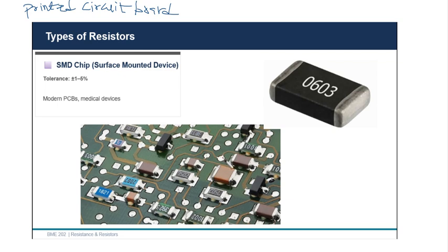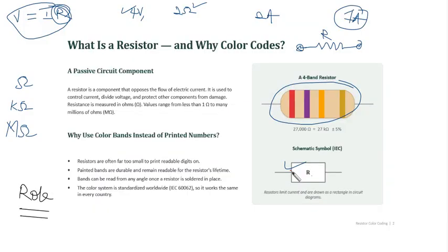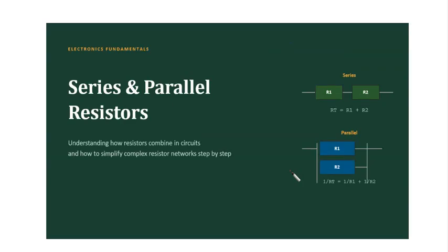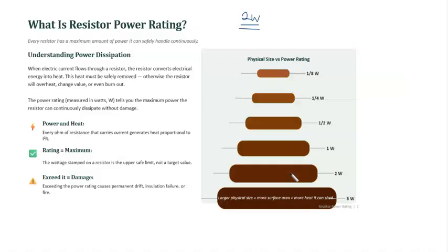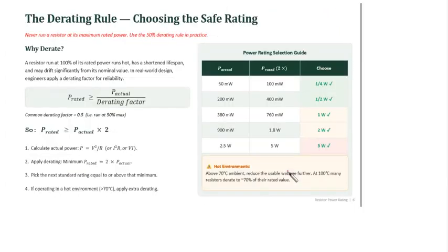Data sheets and documentation usually come with some of these resistors that you can easily reference. So when you look at an SMD resistor and you see this code there, you just consult a data sheet based on the IEC standard, and it will tell you what the power rating of that particular resistor is. So SMD resistors follow a different pattern to be able to decode their power ratings.